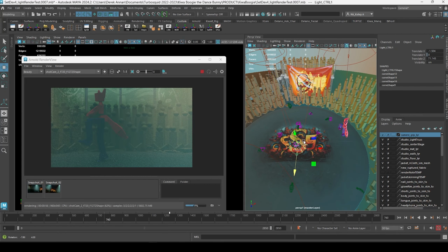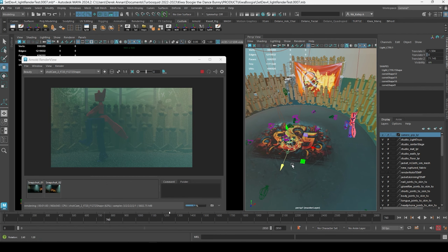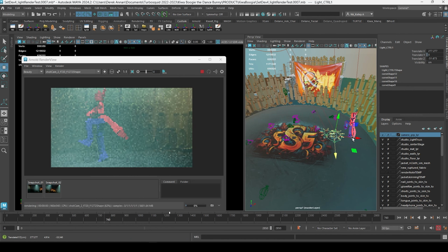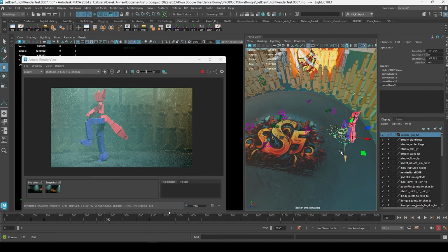As I'm testing the main lights, I always make sure to use the global control to get the lights to the character. Right? When it's time for the animation, I'm considering constraining this global light control to the character's global control, and that way I can control the individual lights and I can know that the master control is always following the character.